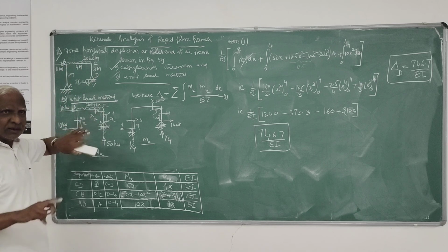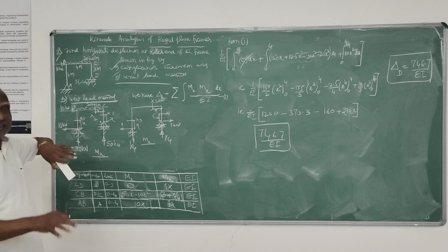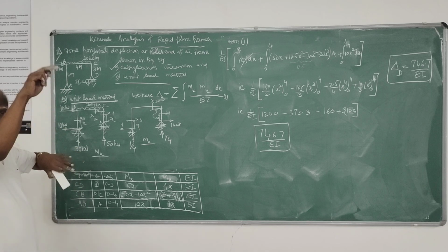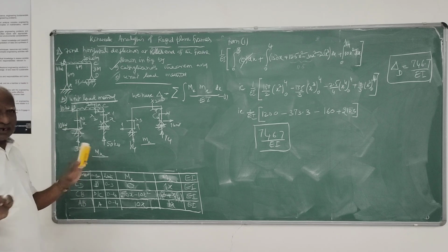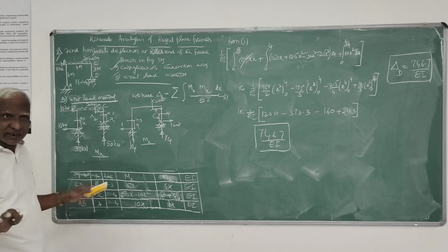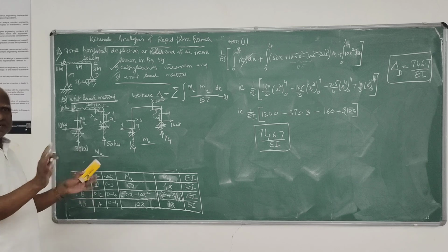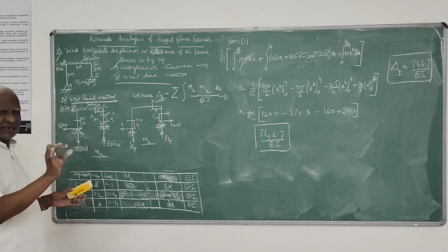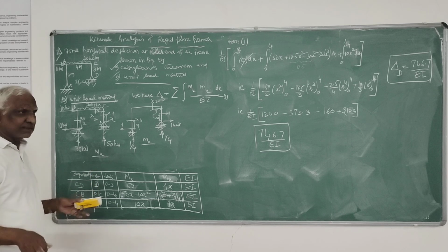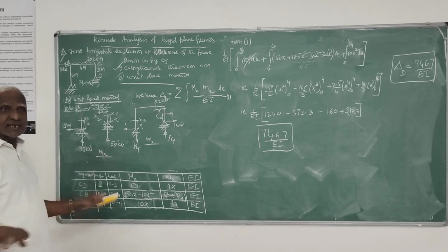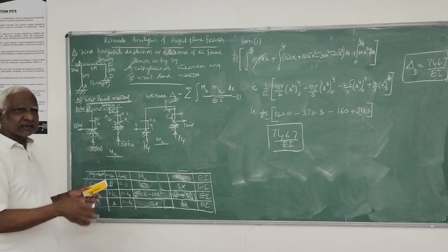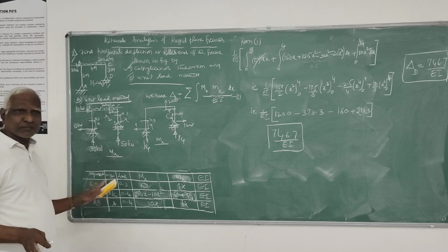UDL also is not possible. Either one moment and find the slope, or one vertical load and find vertical deflection. So vertical load and slope, you cannot do it. Similarly, moment and vertical deflection, you cannot do it. Cross verification, cross determination will not be possible in strain energy. Whereas this is a generalized procedure, you can do anything, either slope or deflection or any type of load.